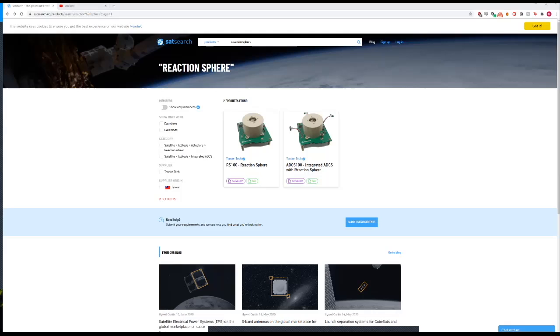Yeah. So the unfortunate answer that is the most true is that it depends. But the answer you actually want is probably, off the top of my head, the back of the napkin calculation says that a 180-degree slew out of a beefy magnetorquer is probably going to be on the order of a couple minutes to complete that maneuver.